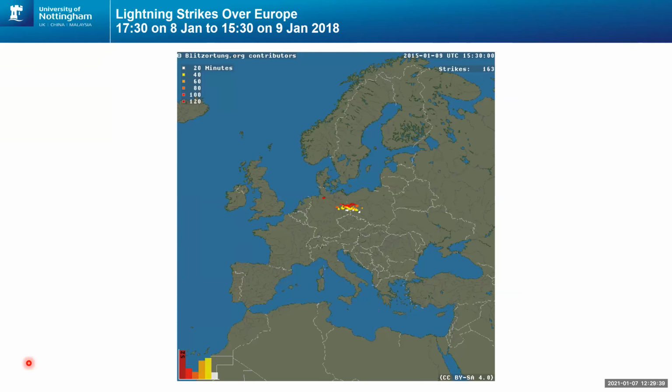And it just happens that we're getting a series of strikes occurring in the Forth estuary here at exactly the point when we measured that extreme response on the bridge. So our supposition is that there was a squall line passing the bridge, which was generating extreme convective activity associated with thunderstorm cells that caused the gust front leading to that extreme response.